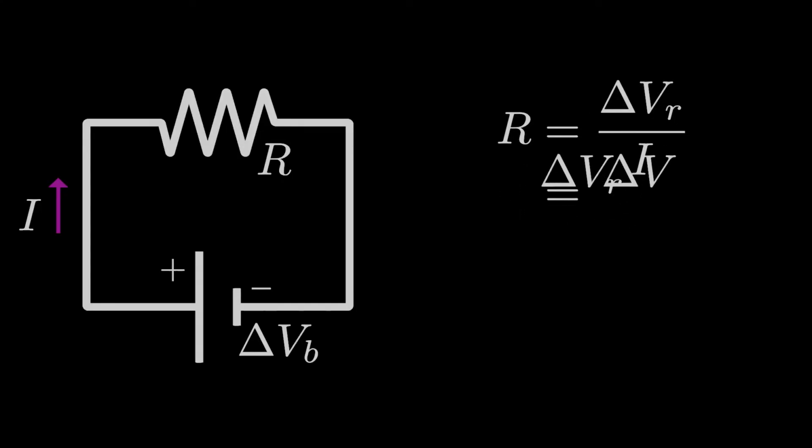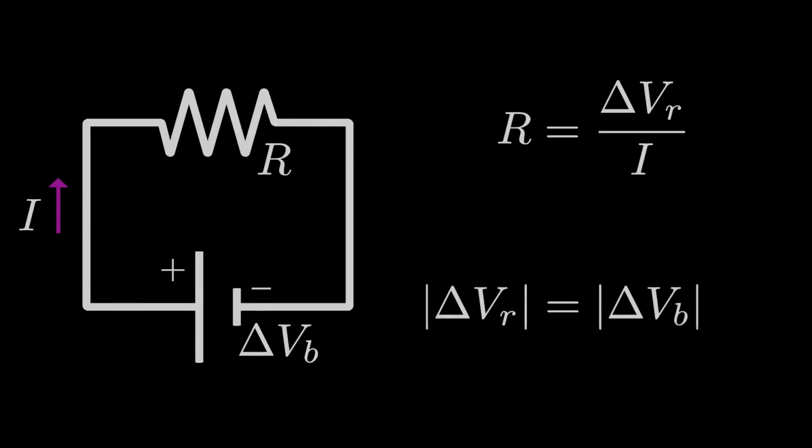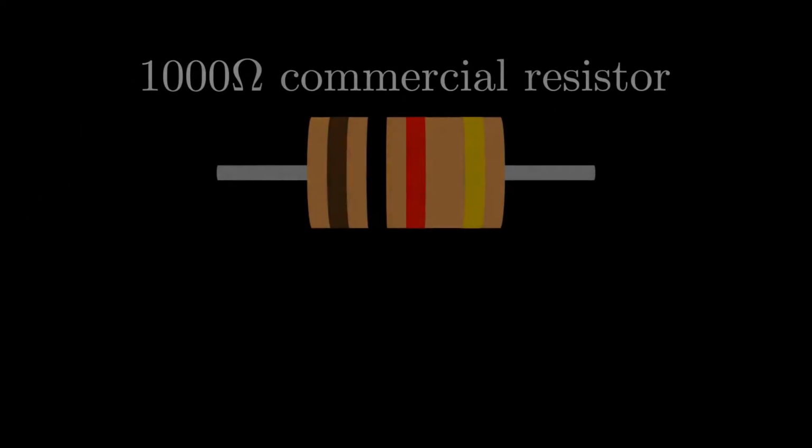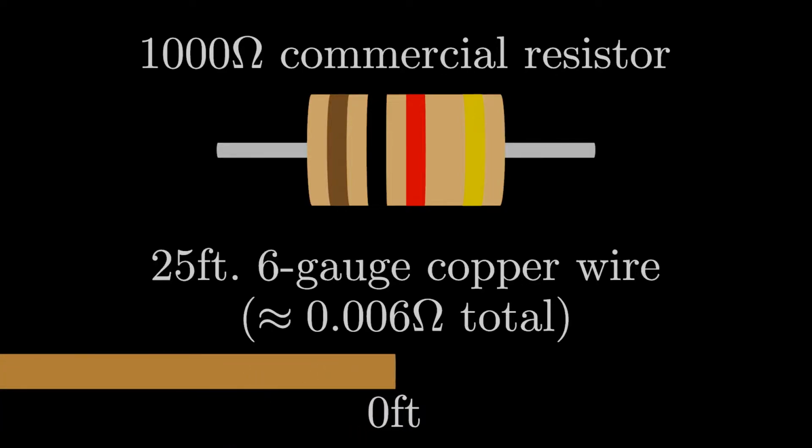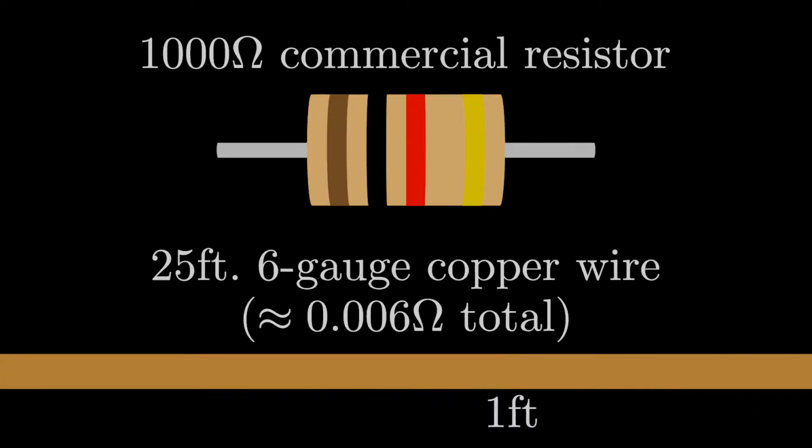In this case, the potential difference across the resistor is just whatever the potential difference across the battery is, up to a sign. What we usually do in circuit theory is treat the electric potential across empty conducting wire as just staying constant. That means the electric potential at point P1 here is the same as the electric potential at point P2. The reason why is the resistor's resistance far surpasses the amount of resistance in the empty wire. We design empty wire by itself to have small resistances by keeping a large cross-sectional area and a small length.